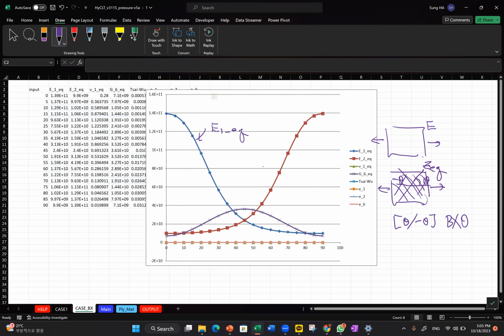Theta. And if it's a zero angle, we have a very high stiffness, because as theta equals 0, we have this much layup, right? So if we have 0 and so on, as you can see, there is a drop like this, and in this direction there will be the opposite, with a symmetry with respect to 45 degrees.